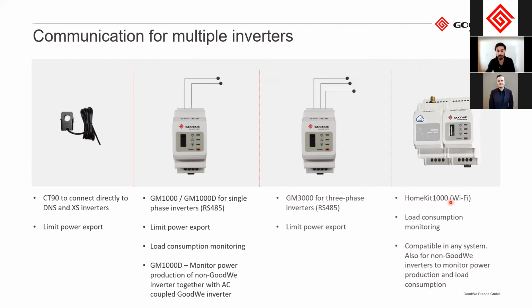And it can also be used to, maybe before you install an inverter, you can install a home kit to measure the load consumption, and from that one you can check exactly when the customer is using energy and how much, and from that you can then size the PV system.